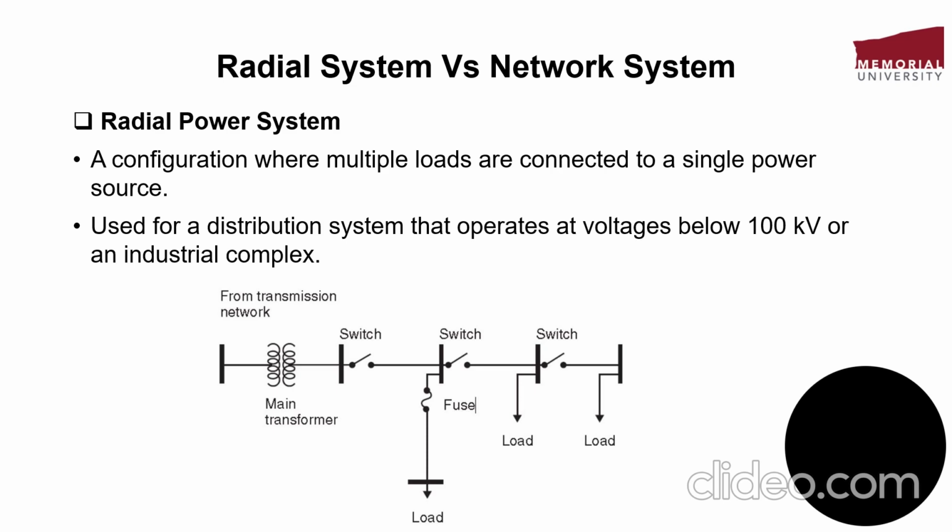Even though the radial power system is a less expensive setup, this configuration has reliability issues, since if the power source fails, all the users downstream which are linked to it will lose service and will be out of power supply. To address this concern, either mainline reclosers or other sectionalizing devices can be used to open and disconnect loads downstream of the switching device during faults on specific line sections.